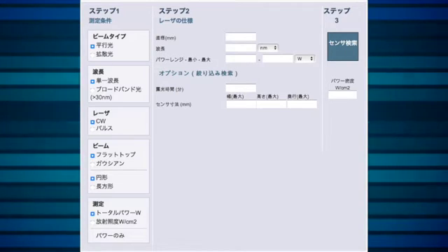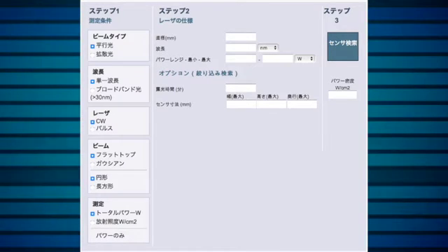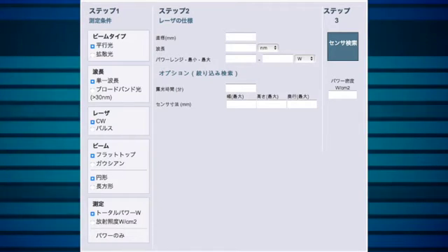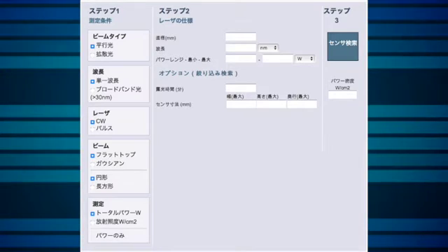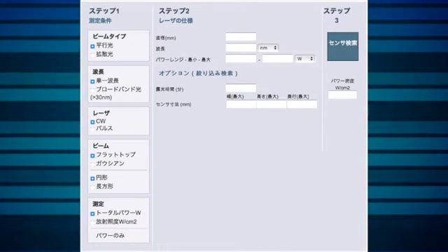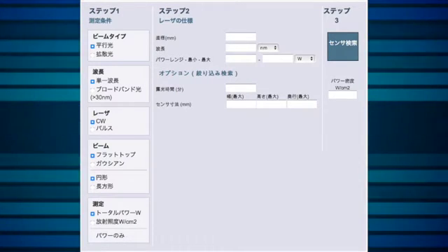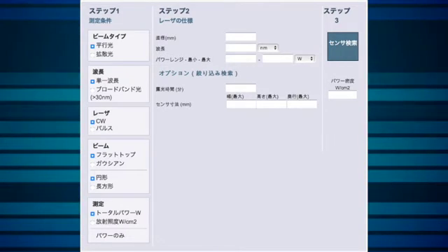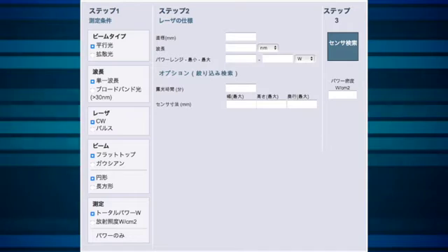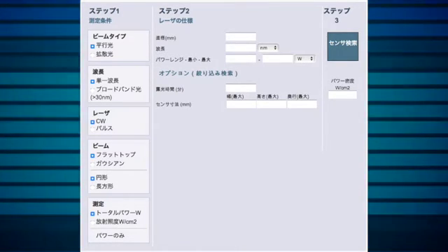This LED Sensor Finder includes all the features of the basic sensor finder, with added options for diverging beams, broadband wavelengths, and measurement of irradiance or power density. In many LED applications, such as UV curing or antibacterial treatment, the parameter of interest is irradiance in watts per square centimeter incident on a surface, rather than the total power emitted from the source. So the LED Sensor Finder has this option built in and can recommend sensors specifically for this type of measurement.